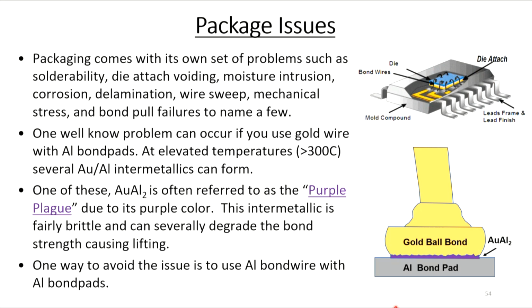Packaging issues. Packaging comes with its own set of problems, such as solderability, die attach voiding, moisture intrusion, corrosion, delamination, wire sweep, mechanical stress, bond pull failures, just to name a few. I don't have enough time to talk about all these, I'm sorry. I'm just going to hit on some of the more well-known ones.